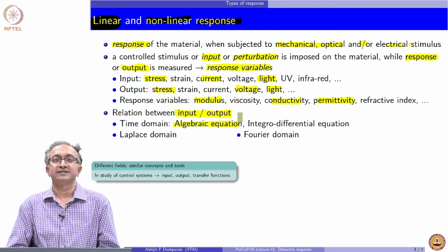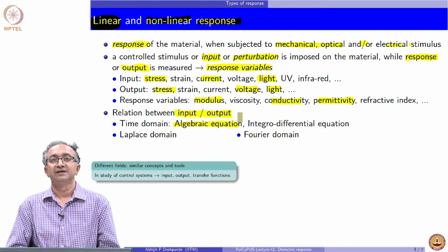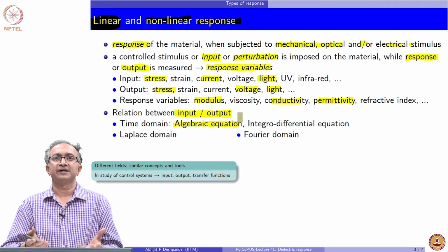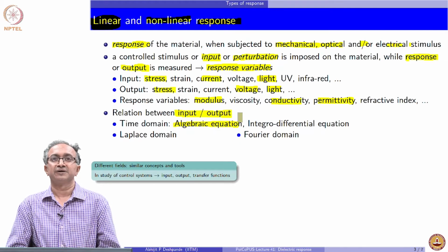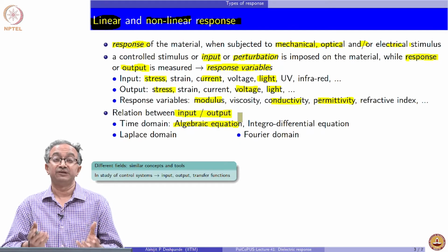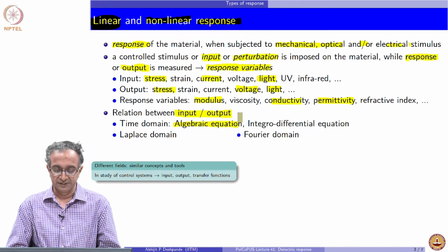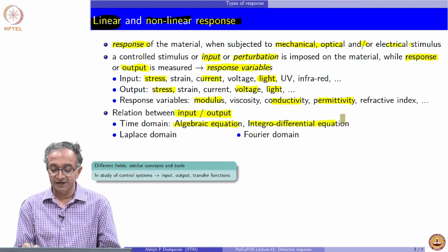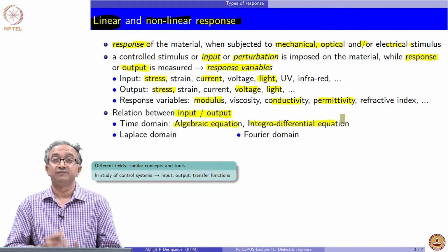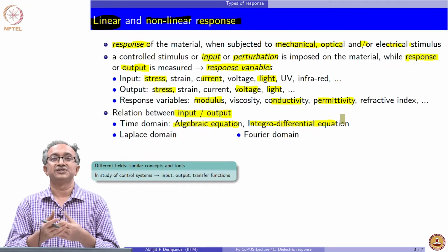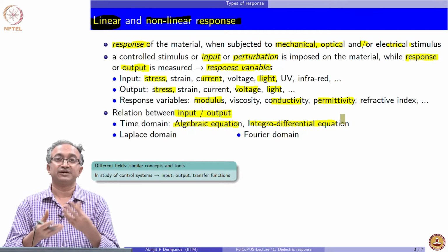So, Hookean law of elasticity is basically that. It could also be a little more complicated, like what we saw for a neo-Hookean model for a rubber-like material that we saw when we looked at mechanical properties of polymers. We will soon see that many of the viscoelasticity models are differential or integral equations, because we have rates of quantities involved, rate of change of stress or rate of change of strain.